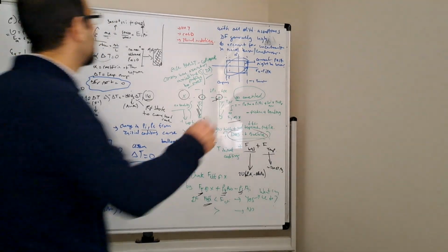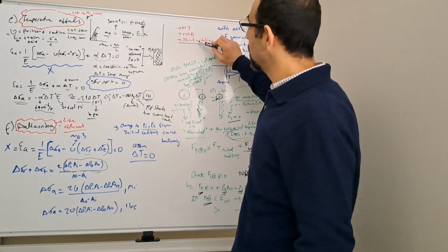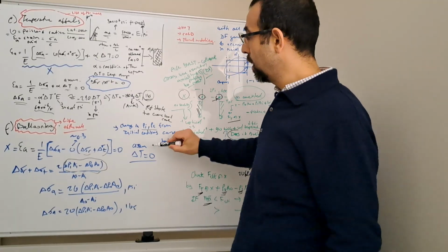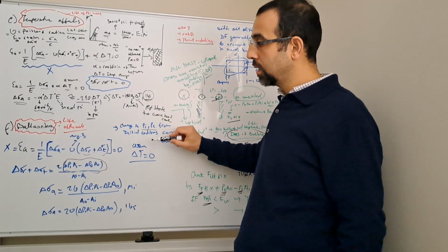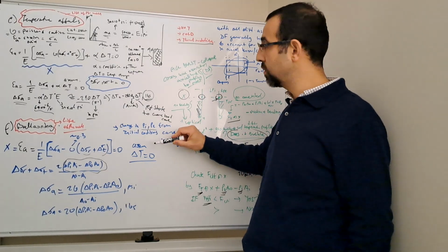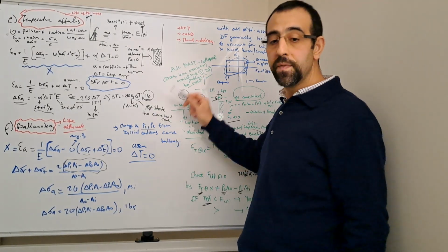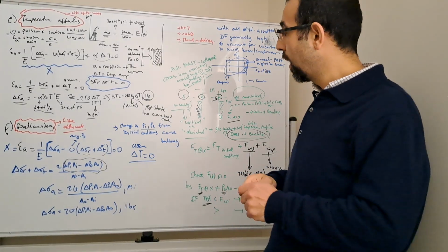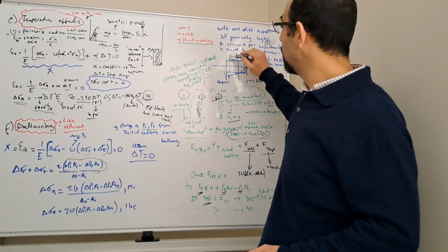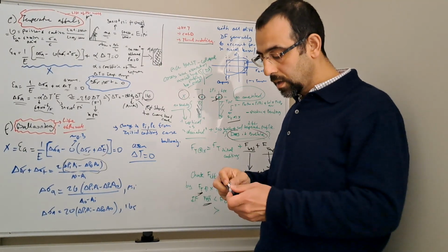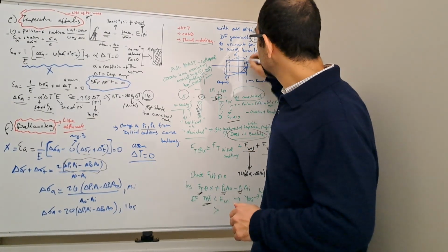Again, we didn't cover the thermal modeling, but it is quite important, especially the temperature-related change in tension. An increase in temperature induces a lot of compression, and vice versa. That becomes important if you have casing whose connection performance ratings are lower in compression and in tension.